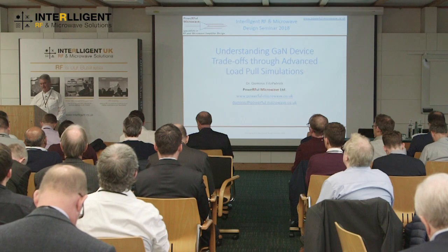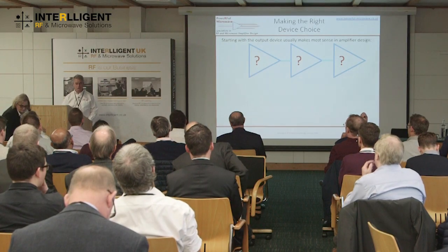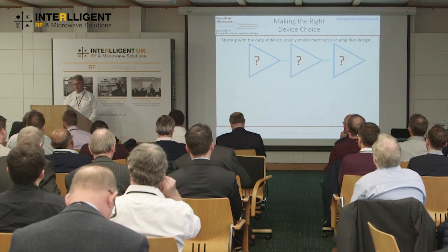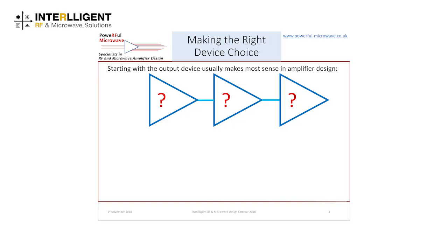Good afternoon, everyone. In this presentation, I hope to describe to you how we can use Loadpull simulations to help with the optimum device selection for power amplifiers. Although I'm concentrating on GaN devices, the same process could be used for LDMOS. When faced with a module or system specification involving PAs, it's usually best to start with the final stage.